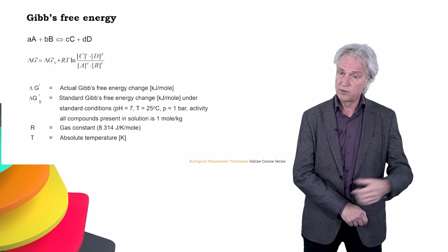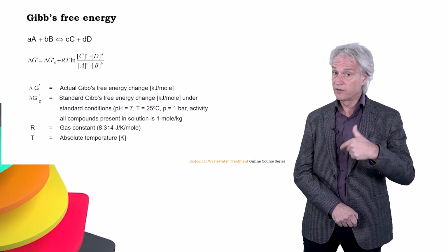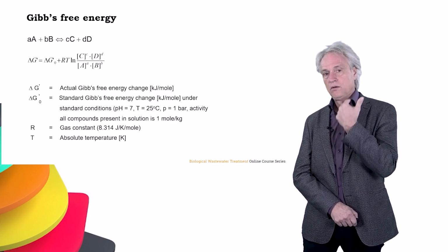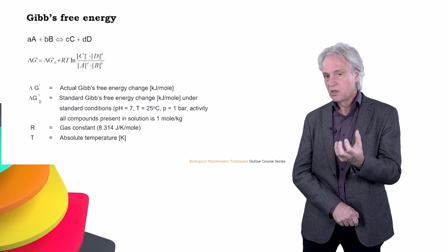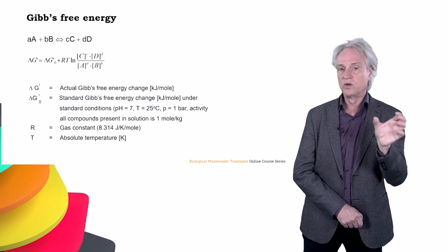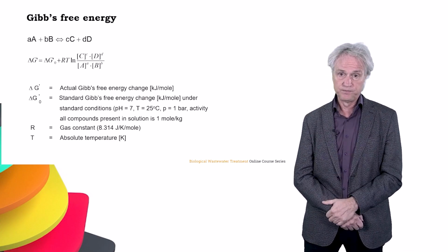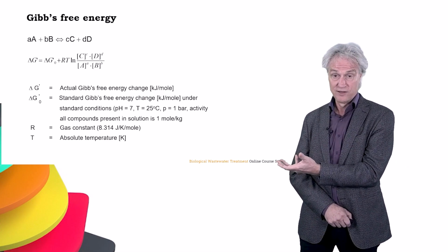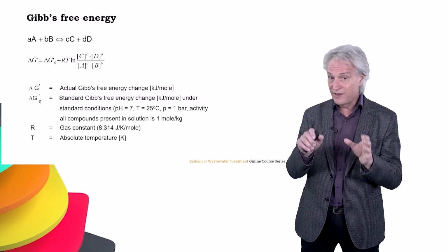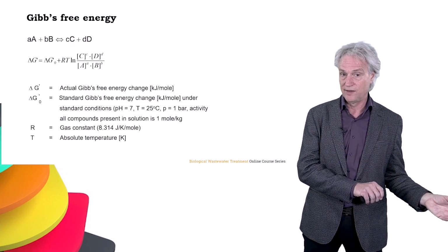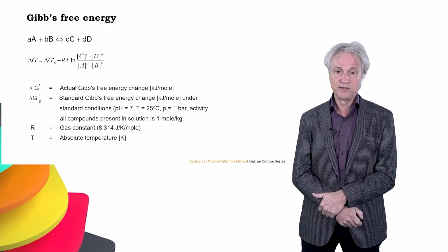And if you do remember, propionate oxidation delivered 3 moles of hydrogen. And that's why, if we accumulate hydrogen, propionate oxidation is one of the first VFA conversions that will be retarded. The presence of propionate in the effluent of an anaerobic reactor is therefore a sign that the balance is not completely alright between the acetogenic bacteria and the methanogenic bacteria.